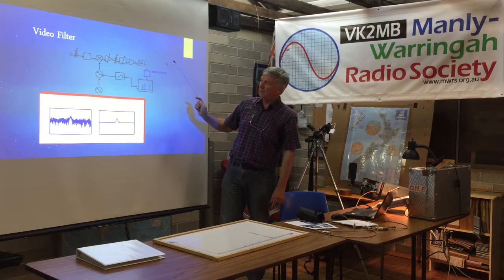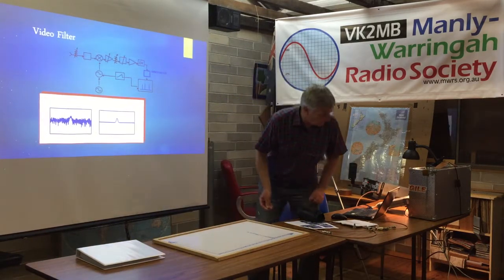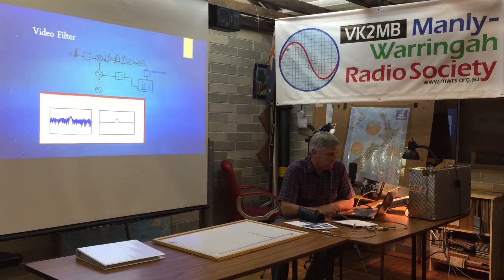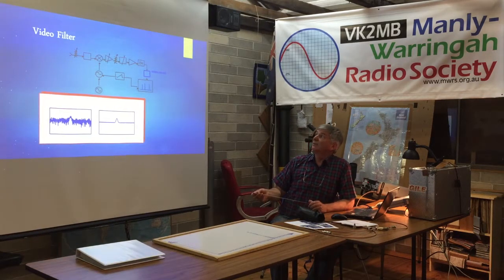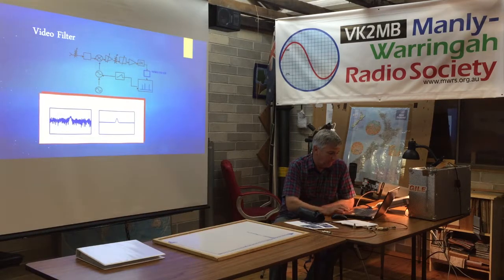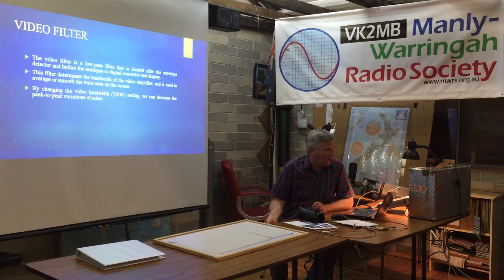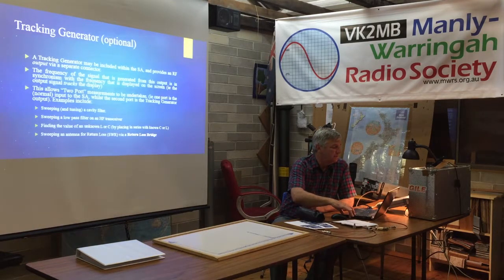I think all spectrum analysers would have variable video filters, variable filters to give you different degrees of filtering. Again, it's just a logarithmic amplifier. I don't want to draw this out and torture everyone by going on for too long. So that's it. It's just a low pass filter, basically, just for cleaning up the signal and smoothing everything off.